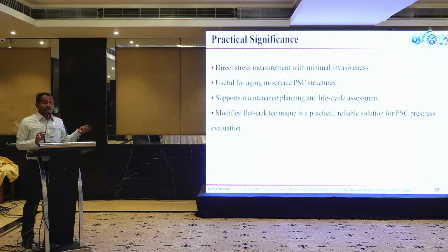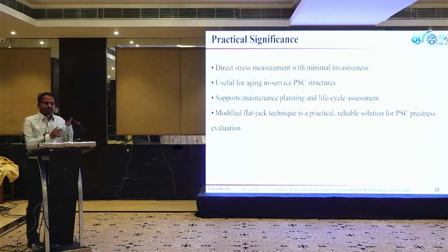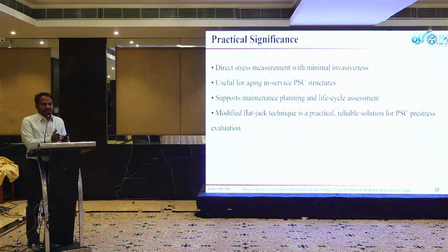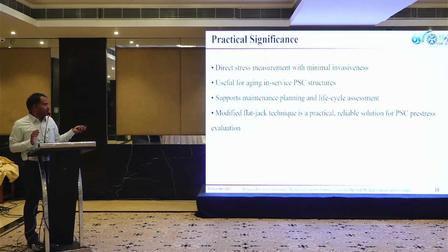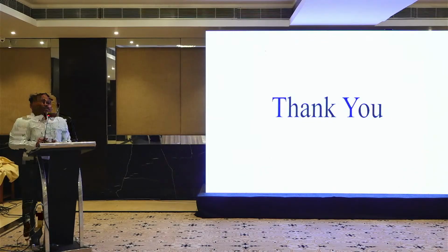It supports maintenance, planning and life cycle assessments. Once you know the value of residual pre-stress, you will be able to do the strengthening or retrofitting schemes. Nowadays, pre-stressed concrete is strengthened based on random numbers. So this will give you a clear idea, because random numbers may sometimes be lesser, and that will damage us. So the modified flat jack technique is a practical, reliable solution for pre-stressed concrete evaluation. Thank you.